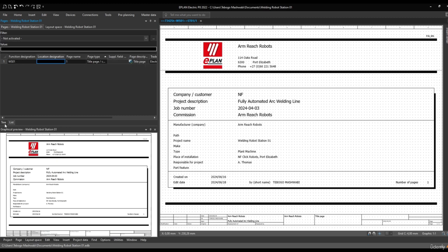So I prefer the Tree View, and I know most people prefer the Tree View as well. It's the best choice, as I said, because it has icons that let you differentiate which structure identifier you are sitting on. Eplan also allows you to sort your pages according to structure identifiers. So maybe, for example, you want to view the installation sites as the first pages, and you want to view the mounting location as the last pages. You are able to sort this out.